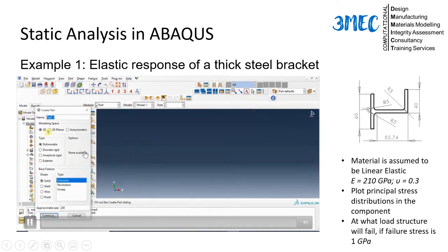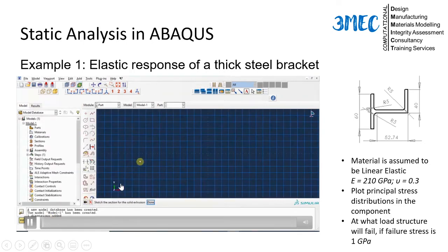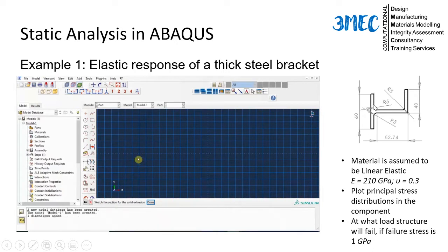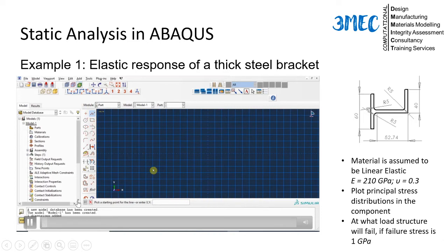You can see, I will just go through it. You will start with the part, as I explained to you. You can do it with 2D, but in this case we're going to go with 3D and extrusion. What I have done in this case is create a center line for this whole section, and then I will offset the lines, trim, and then create fillets so that I will have a sketch out of it. So that's what I'm going to do here.